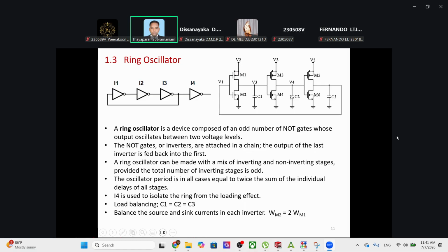You can design this one. Here the capacitance is a dummy load. If you want a dummy load, you can put a reverse-biased PN junction here, for the charging and discharging part. However, you can also put another inverter input, but that inverter's output is idling.